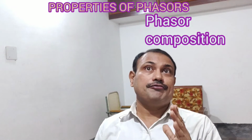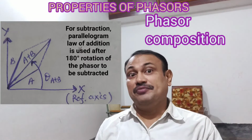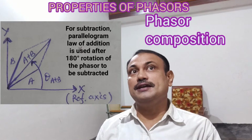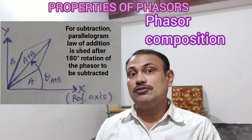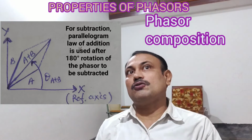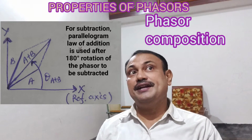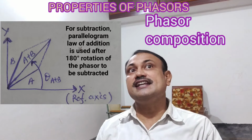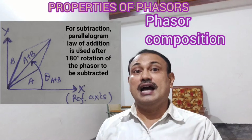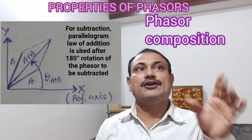In composition of phasors, when two phasors are added or subtracted, the result is a phasor whose magnitude is equal to the measure of the diagonal of the parallelogram formed with the component phasors as the sides of the parallelogram, and the resulting phasor angle is the angle made by the diagonal with the initial reference axis. Here the reference axis is the positive x-axis. And for subtraction, the phasor to be subtracted is rotated by 180 degrees.